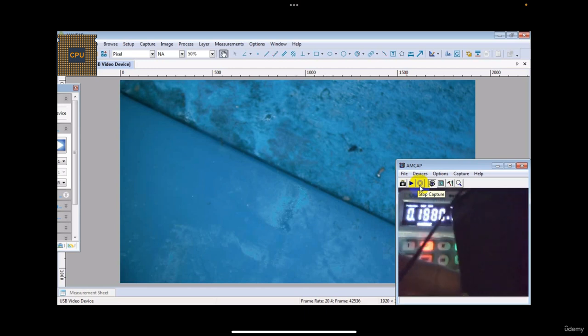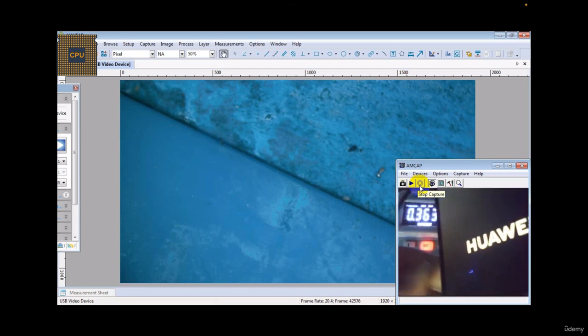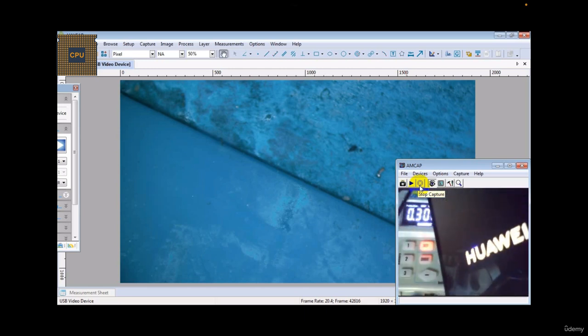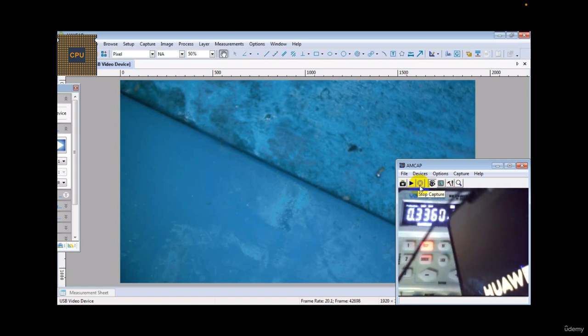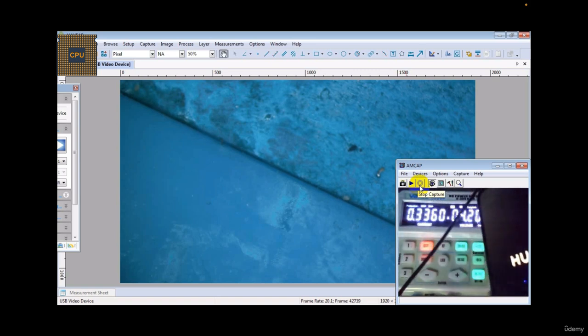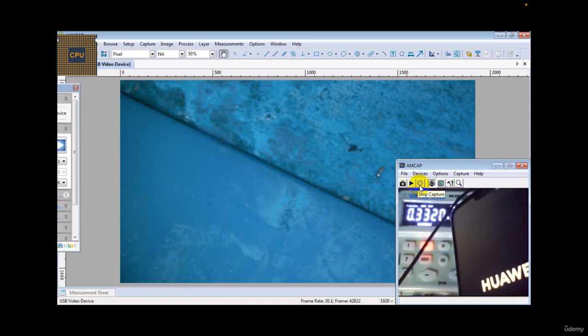First step, we need to know which power line is the cause of the problem itself. Is it the IC power or the CPU or the NAND? Firstly, we will connect the phone to the power supply. If we get an ampere more than 0.1, like 100 milliampere, that means that the IC power is working correctly.